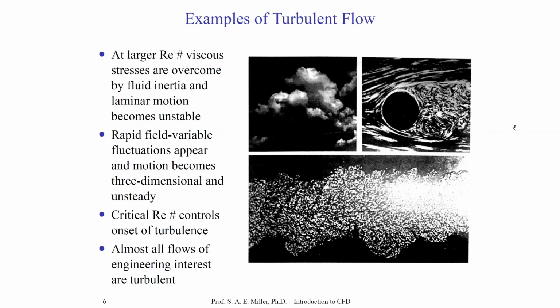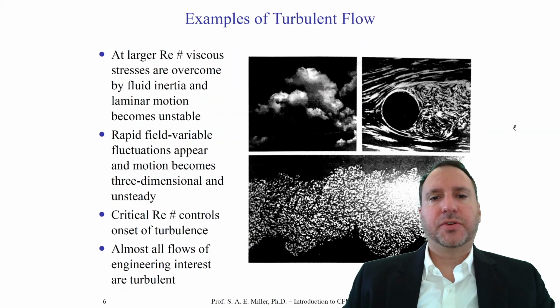It's hard to define turbulence, so we'll do this through some examples of turbulent flow and just discuss them and look at their quantities first. First of all, generally, turbulent flow happens in a three-dimensional regime, which has some viscosity. So, at large Reynolds numbers, the viscous stresses would normally become overcome by fluid inertia, and the flow might transition to turbulence. This is where laminar flow becomes unstable, and the theory of hydrodynamic instability might give us a way to understand these flows and their transition.